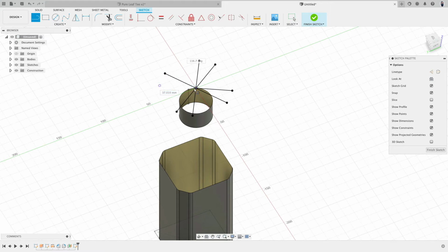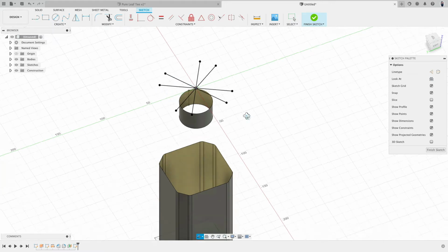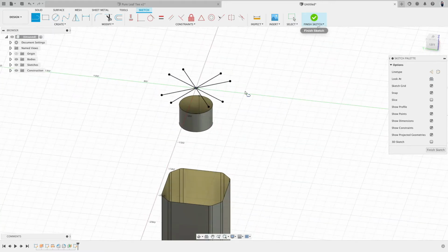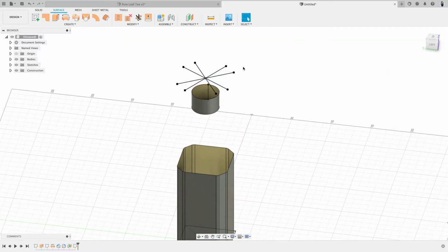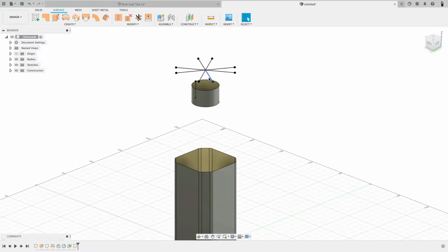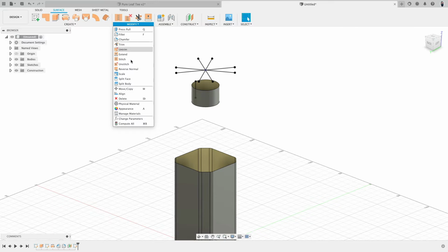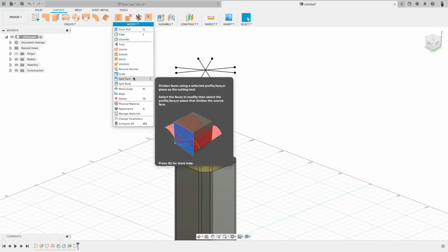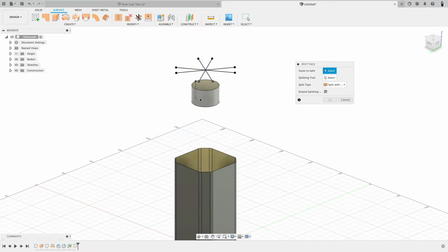You see how this all works together. Really good. Okay. Why did I create these lines? Now with these lines, I use them as a slice tool to slice the face. So this face, slice by this, and on a Mac it's the Command key, or Control on the PC, and slice.